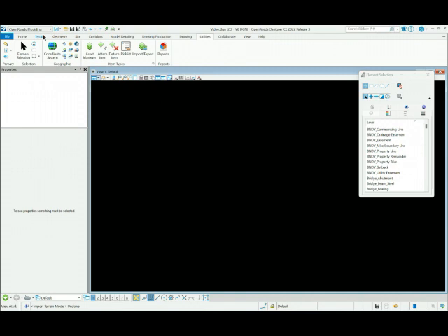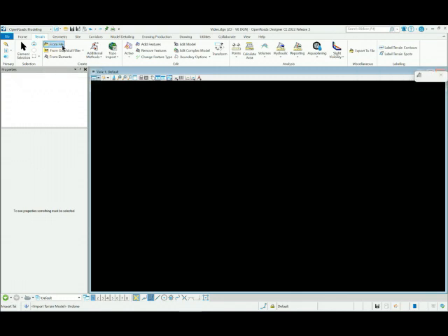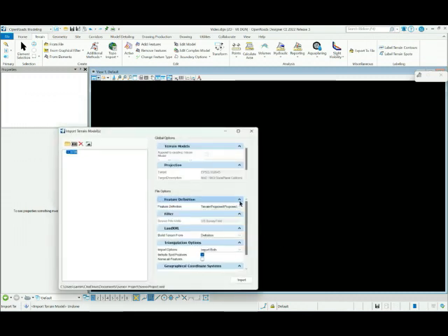Now we could go ahead and start importing our terrain file. So I go to terrain tab and then from file. And then here I'm going to click our XML file, senior project, and press done. The first thing you want to do is make sure that it's projecting to the proper coordinate system, which it is in this case.